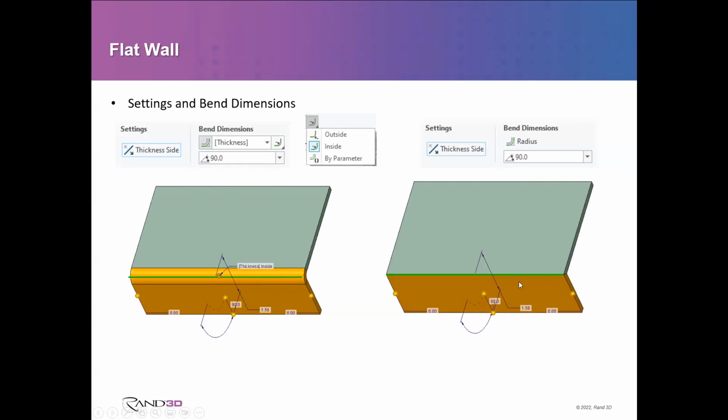It's just going to add the wall and leave the corners sharp on here. Now, if you do that, you will not be able to unbend this. You do need to have some type of radius in that corner to be able to unbend it, but you could come back and add it later if you wanted. But typically, you let the computer do it.